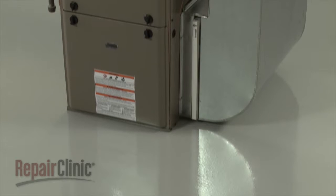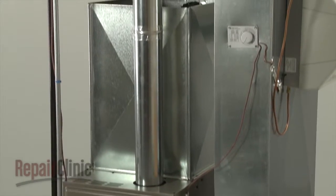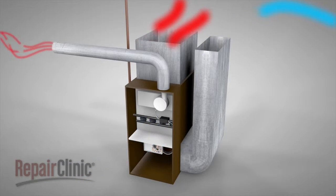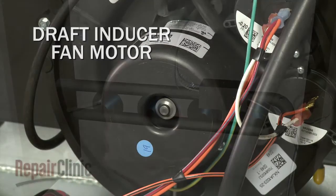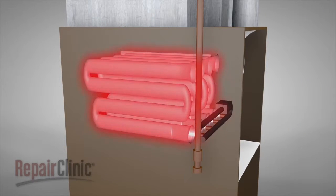Forced air furnaces can be installed to send heated air up, down, or sideways to accommodate the space in which the furnace is to be installed. Gas burners, fueled by either natural gas or propane, are used to generate the heat. Modern gas furnaces have two separate airflow systems, which operate while the furnace is running. The first system uses a draft inducer fan motor to draw air into the burner assembly. The air allows the burners to warm the heat exchanger.